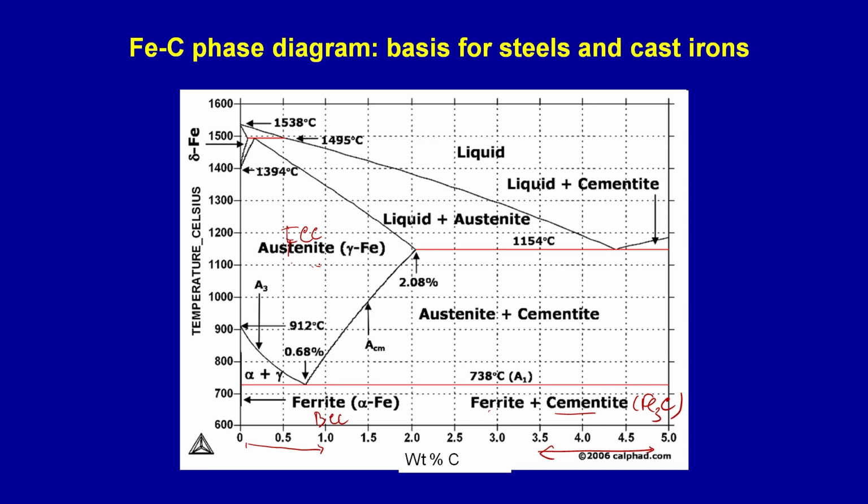Okay. So, in a phase diagram or a phase mixture, you can have either a solid solution or a compound, and compounds can have fixed stoichiometry or variable stoichiometry. But here Fe3C has strict stoichiometry, it has a fixed carbon composition of about 6.67 weight% carbon, and so Fe3C, if you look at it, has carbon about 6.67 weight%, and iron is the remainder, that is about 93.33 weight%. So, the total will add up to 100%.